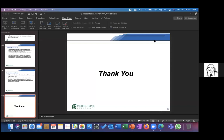I was there for almost 8-9 years, and part of the GT road is always under construction, so there is a lot of overloading on the GT road. In that case, quad piezo can be good for data collection, since we don't have the actual load equivalencies or truck factors. I still remember there is a 1995 NTRC study most people are using, and that is based on a very small sample. It is dangerous to still use it, because the loading might have changed in almost 30 years.